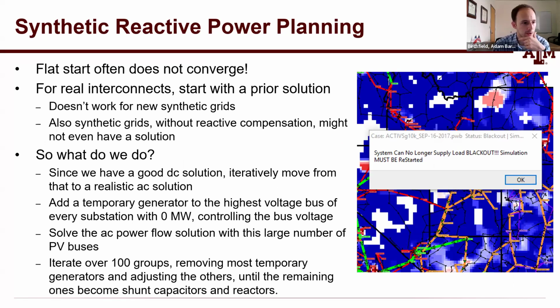And the other one by the same person is, do you need the wind and PV penetration in order to calculate the exact shunt capacitors you need for reactive power compensation? This reactive power planning approach is based on specific load conditions and specific generator dispatch conditions. And as part of those generator dispatch conditions, we do make assumptions about how much wind and solar is in the case. And so, yes, we do consider that. So I think the answer to that is yes.